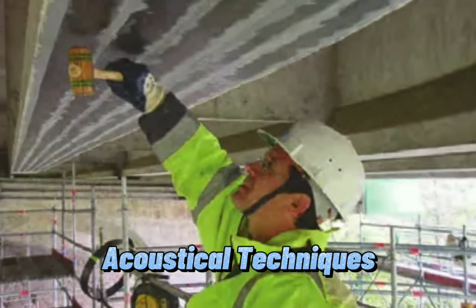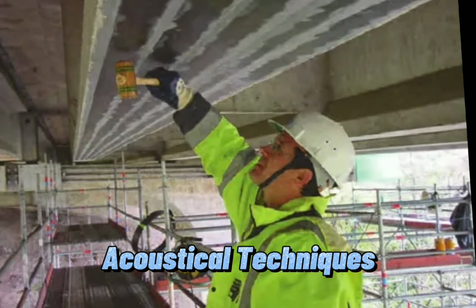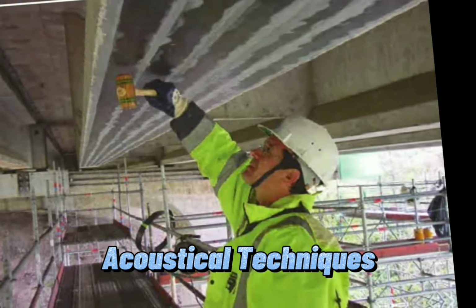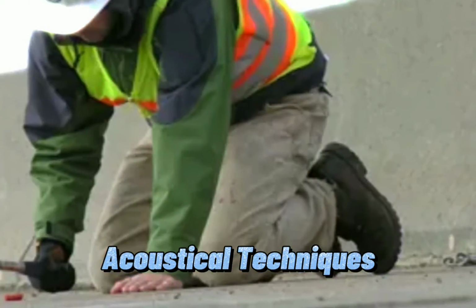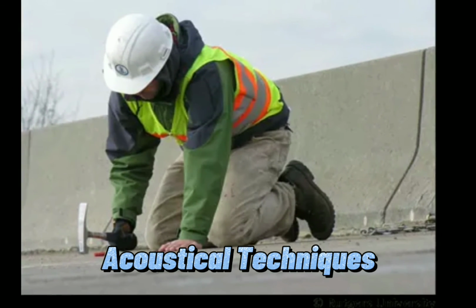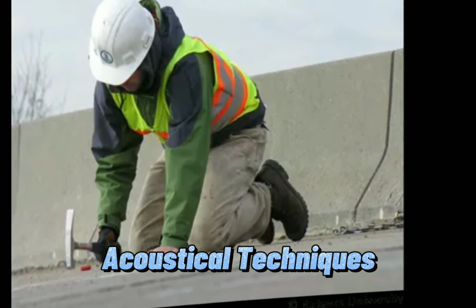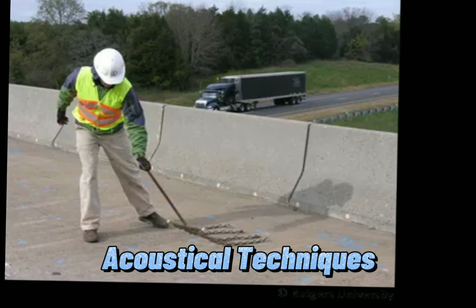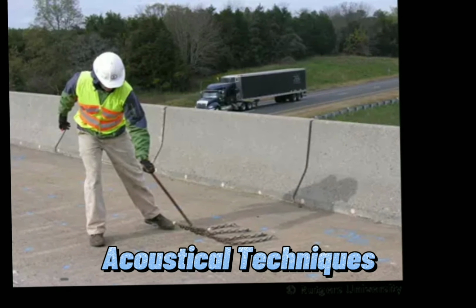Acoustical techniques. Method: this is a non-destructive technique performed using a chain drag or hammer to identify changes in sound pitch. The test is able to detect delamination as well as the separation of coating or the splitting of a structure into layers. Disadvantages of using acoustical techniques: the test may not be accurate due to hearing biases, requiring a trained ear for accurate analysis. Bridges with asphalt overlays cannot be tested using this method.